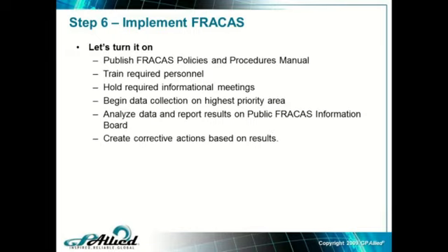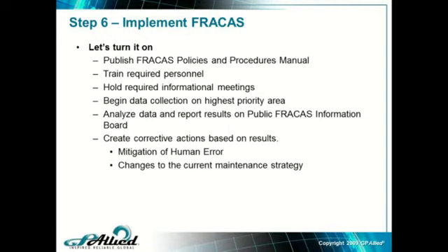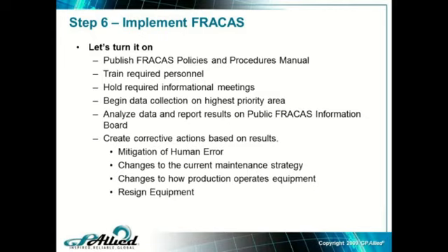Then we want to create corrective actions based on the results. We want to mitigate human error. If we need to make changes to the current maintenance strategy, we need to make them. And then we may need to make changes to how production operates the equipment. I know this may surprise you, but there are many failures that have to do with how production operates the equipment. And some of it should have been redesigned, so redesign the equipment.